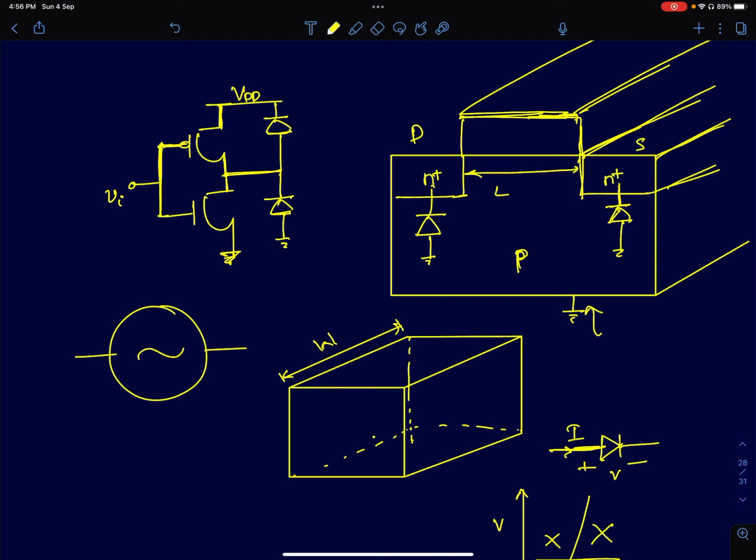What you do is let the PLL lock and figure out what the control voltage is, and then let the oscillator go open. It will just be running in open loop, and this is an idea many companies were exploring at that time. So you need to store an analog voltage onto a capacitor and then hope that this capacitor voltage remains nearly constant, so that within the duration of data transmission, the frequency also remains more or less the same. There are of course some specifications as to how much the frequency can drift, but let's not focus on that.